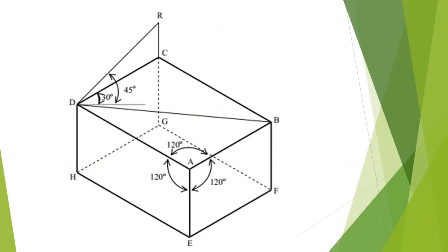Now we will see explanation of figure. 1. It is seen that all the edges and faces of the rectangular prism are equally inclined to the plane of projection. 2. Hence the rectangular faces are seen as similar and equal rhombuses. The three lines AB and AD and AE are meeting at point A. 3. These edges are mutually perpendicular to each other in the solid.